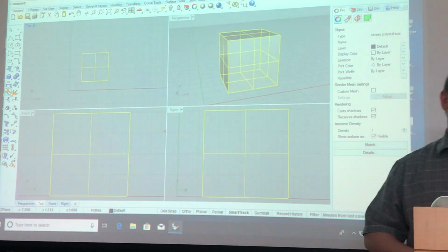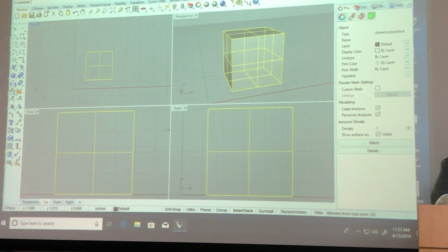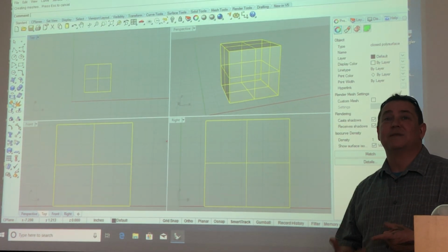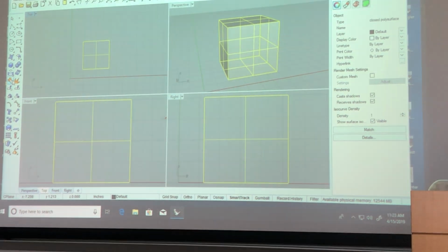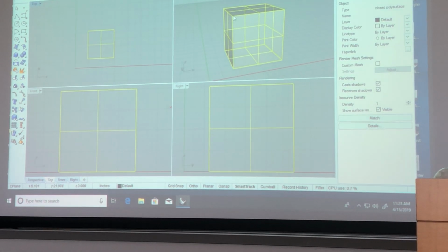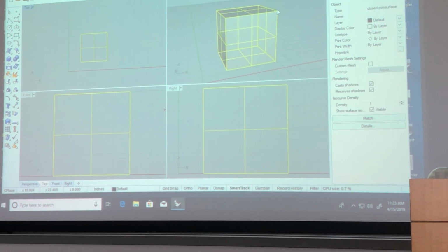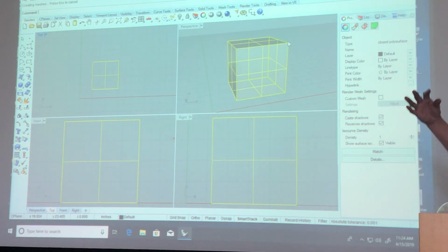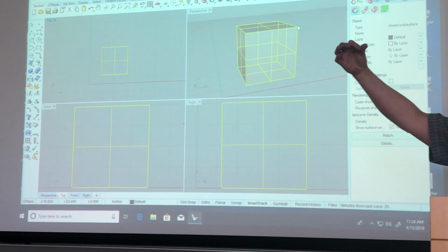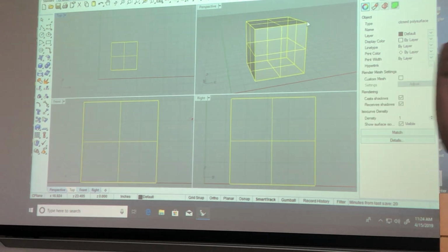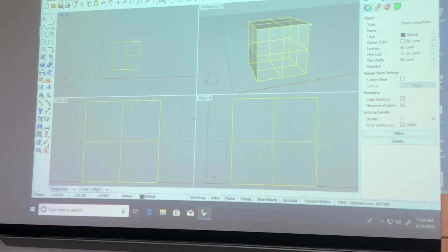It will only work right if there are 0 errors in those surfaces. Meaning, the corner of this surface and this edge of this surface touch each other within a 10,000th of an inch. There can be like no error in the drawing.